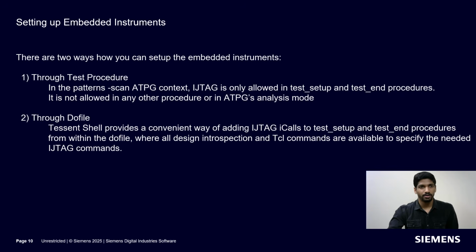Moving on to the main part, setting up the embedded instruments. There are two ways how you can set up the embedded instruments. The first one is through test procedure. Please note that IJTAG is only allowed in test setup and test end procedures, not in the ATPG's analysis mode. And the second way is through Dofile.